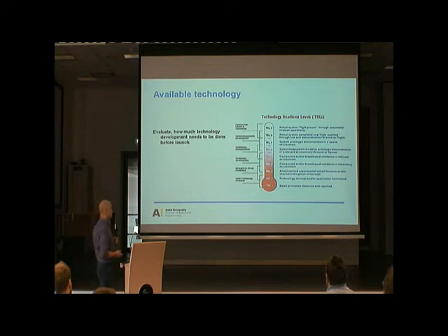And if you just have a basic principle observed and reported that something can be measured through this phenomena, then technology readiness level is 1. And technology readiness level is 9 if you have it already operating on one satellite, measuring the thing and delivering the data. And you want to use exactly the same instrument on a different satellite, but measuring the same thing, just more frequently. So this is a technology readiness level 9 for this instrument then. And all these things between, like breadboard versions and everything, have their own technology readiness levels.